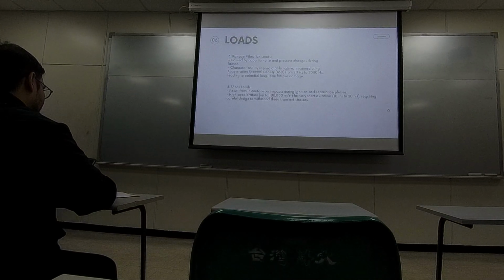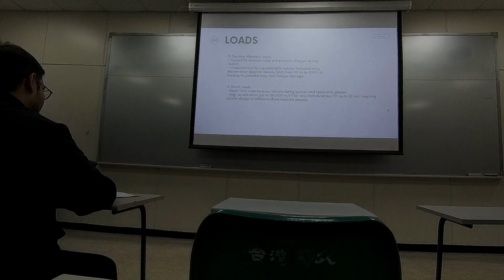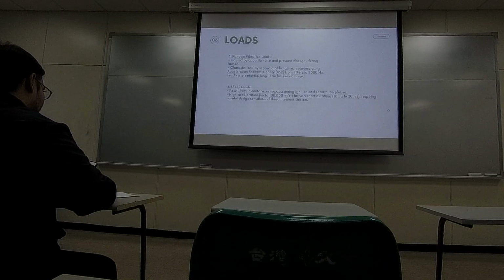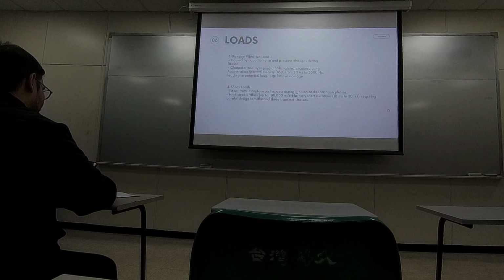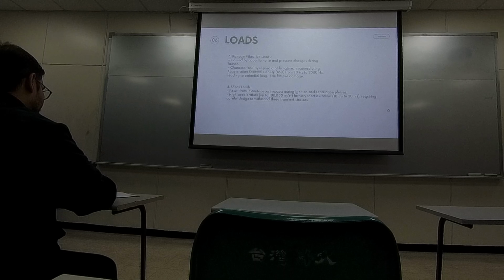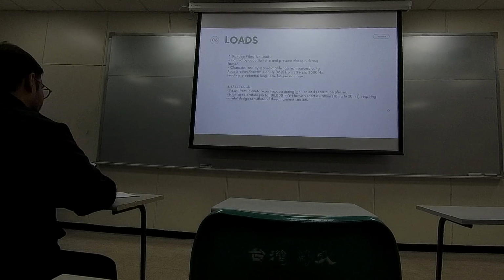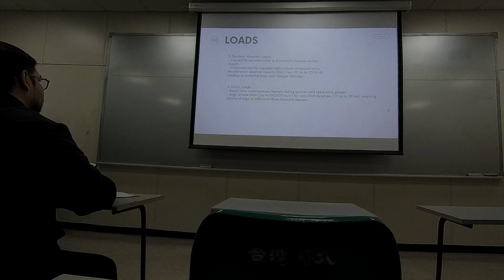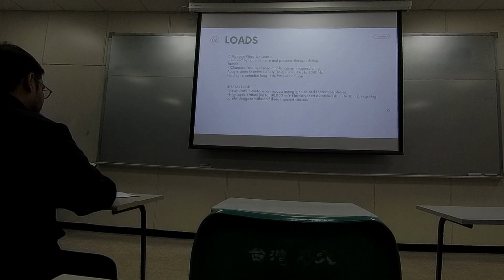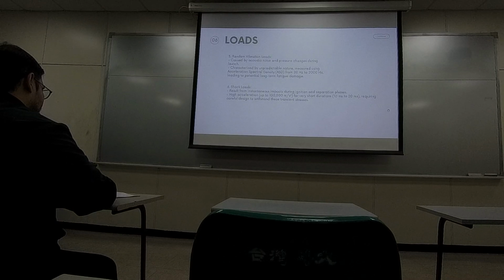And the third is random vibration load. It is caused by acoustic noise and pressure changes. It is characterized by its unpredictable nature, measured using the ASD, which is acceleration spectral density, from 20 Hertz to 2000 Hertz. This kind of load may lead to potential long-term fatigue. And fourth, shock loads. They result from the instantaneous impacts during ignition and separation phases. Because shock loads have a high acceleration during a short duration, they require a strong design to withstand this kind of force.